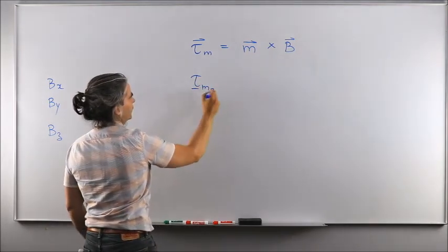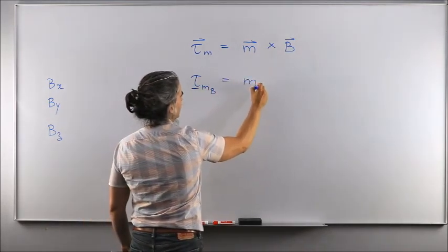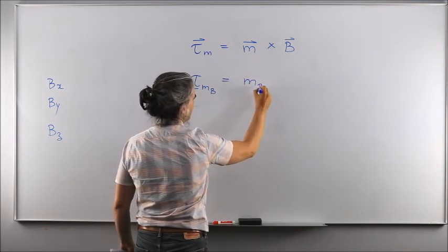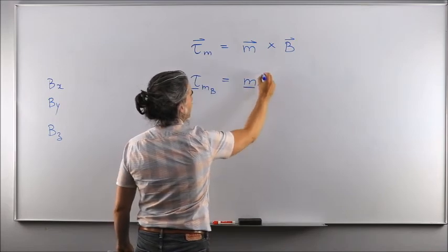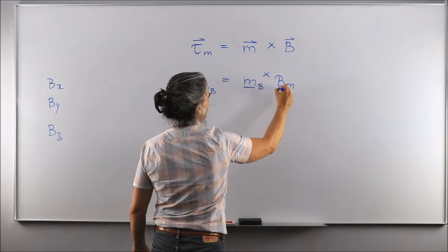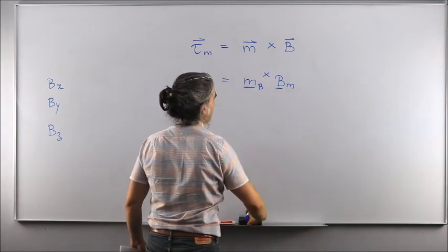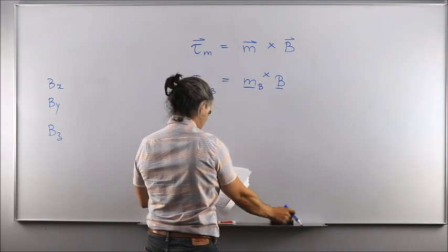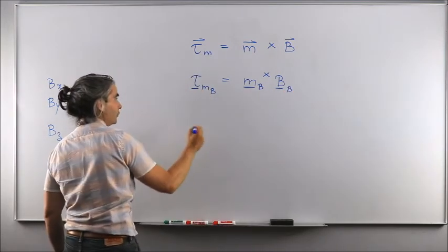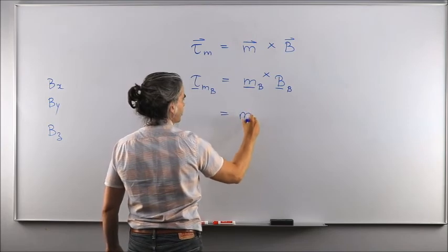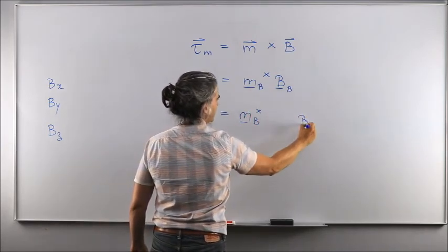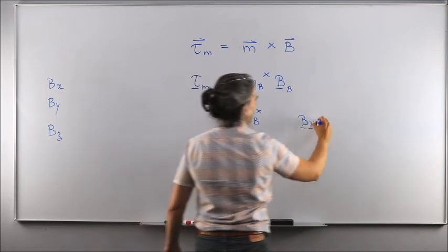And then I'm going to write T_MB equal to the magnet, if you will, created by the internal electronic components of the spacecraft. It's skew symmetric, applied to the components of the magnetic field in the body fixed reference frame, denoted by B subscript B. Now, so far we had obtained analytical expressions to calculate the field of the Earth, but in ECI, right?